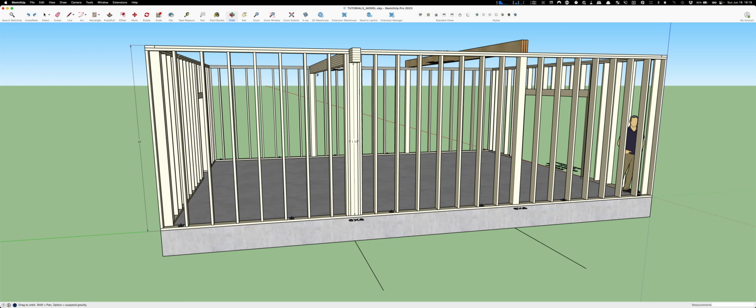And if you make it exactly 10, let's just say that's what happened, you could run your sheetrock and you could get 8 feet and then you got a 2 foot rip. But when you get that exact, some of these things don't fit easy. And when you're 8 foot 1 1/8 or 10 foot 1 1/8, you get a little bit of play, so you can put your lid in, and then you can butt your wall up to the bottom edge of your lid, and you still got room at the bottom.